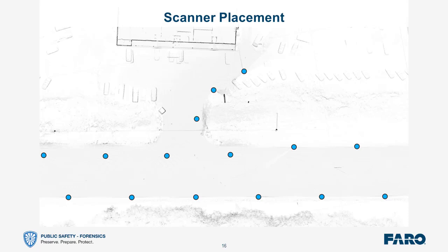What's also important to point out in this case, and I do have an example of this later in the slide set, is that when the scanning was taking place here, it was not set at 360 degrees, so the horizontal scanning area was reduced to 180 degrees, which really means that when you're standing on the shoulder, you're not capturing any data behind you. You're only capturing data in front of you.